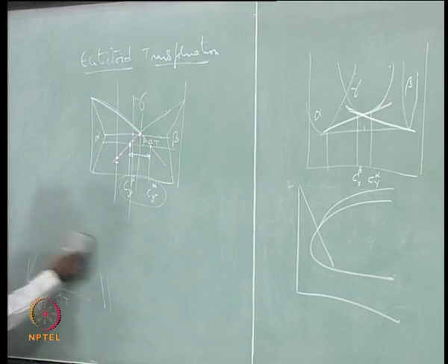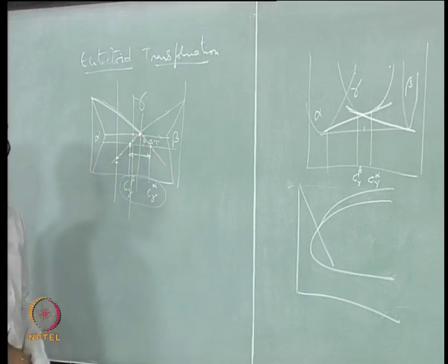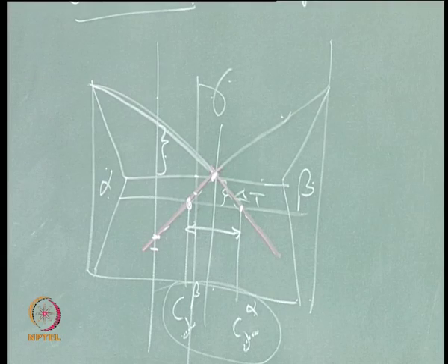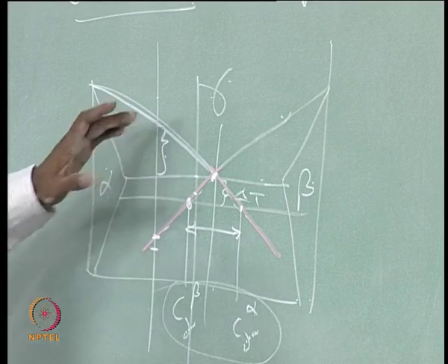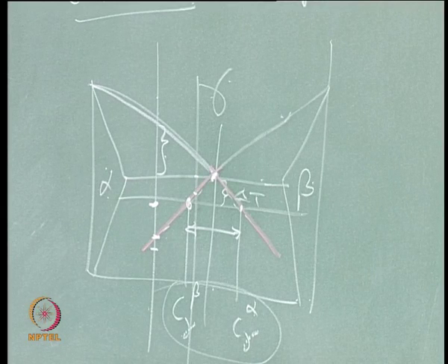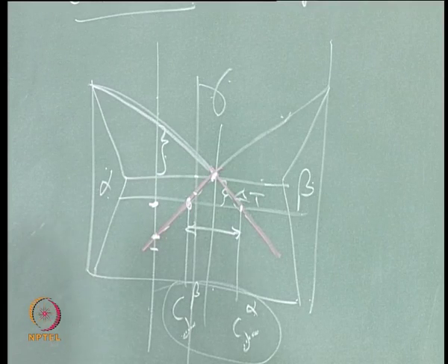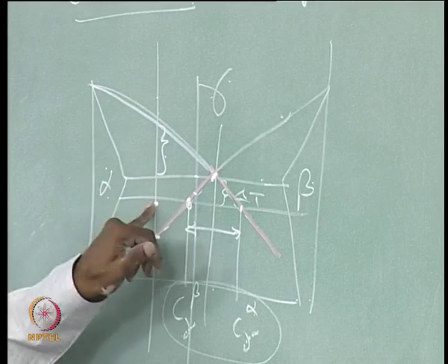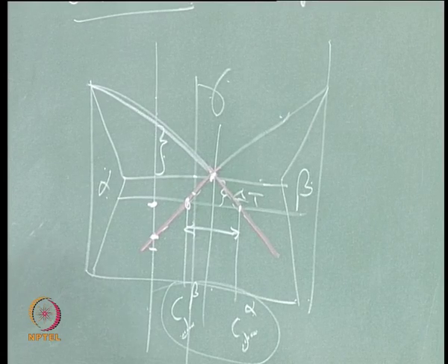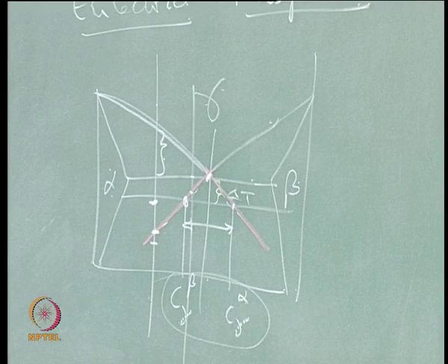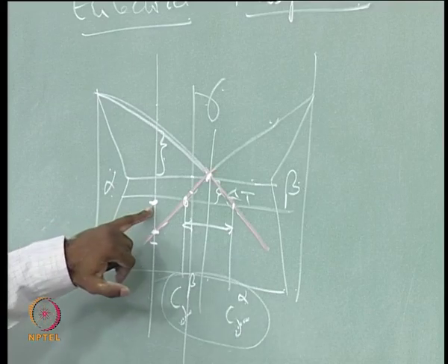The second issue is, if I take this alloy and I am cooling it, the alpha that is forming here, what would be the morphology of that alpha? People usually see whether the alpha forms there or alpha forms here. For example, if I have undercooled this alloy to this temperature, still you will have an alpha forming, because it has not yet intersected this. So you will have an alpha forming even if you have undercooled it below the eutectoid temperature, not simply cooled it. If you have simply cooled it, by that time the eutectoid transformation is already over. So if you undercool it to that temperature, you can still get alpha.